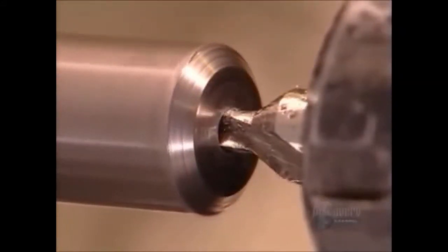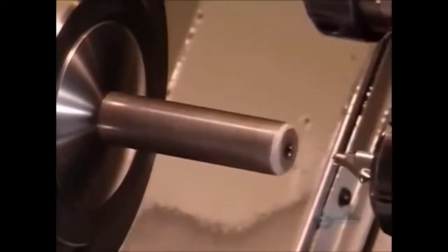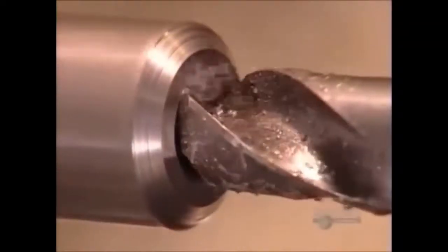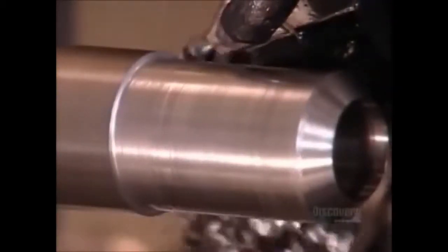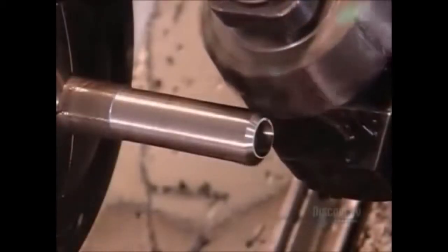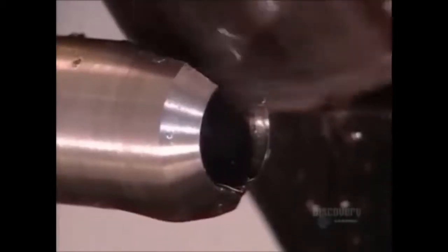The same machine makes plug cutters. Its center drill makes a starting hole, but this time, the main drill doesn't bore right through. It stops at the depth that the plug cutter is designed to cut. Just as before, the rough turning tool shapes the body, and the milling cutter sculpts the 4 blades.